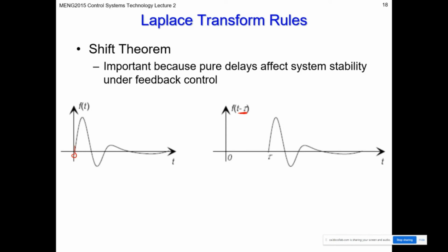If you were to take a human control system, you could be a pilot or a driver of a car, and this gap here, the tau, the delay, is due to reaction time, right? But more typically, we'd be dealing with a system that might be the flow of fluid in a pipe. So you open a valve at one point in the pipe, and you're measuring the pressure at another point in the pipe, and the pressure is going to stay 0 for a while after you've opened the valve because the fluid actually has to move to the point where the pressure is measured in the pipe. Right? So that's a good example of transport delay.